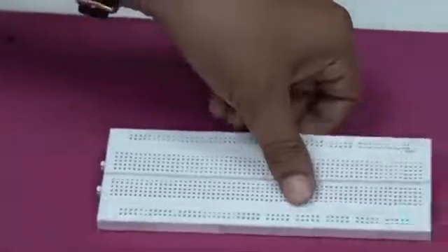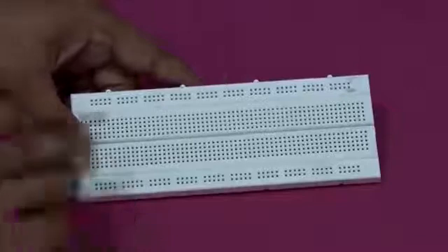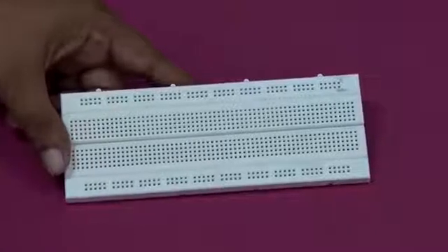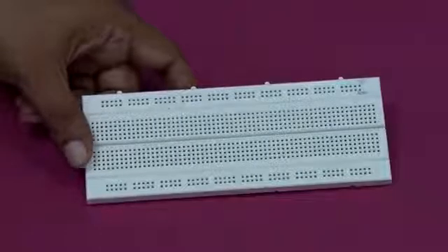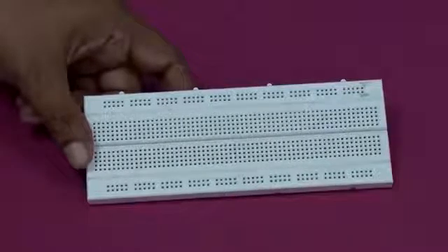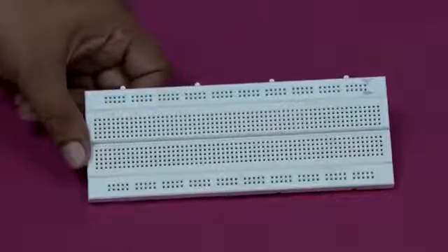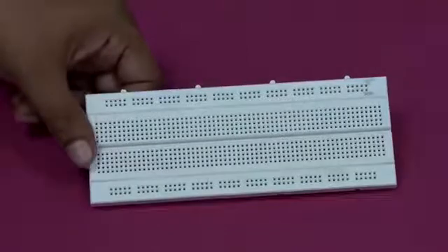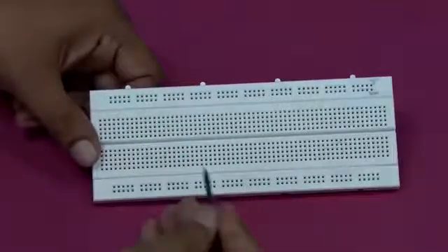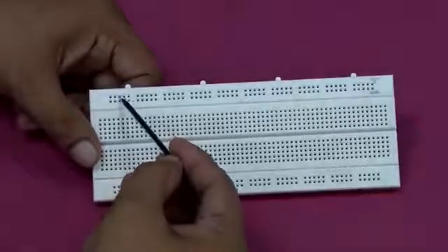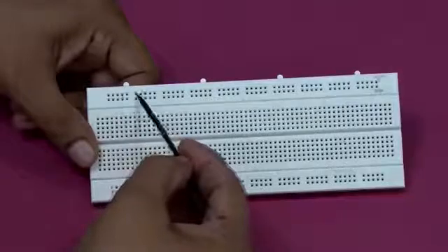So, now Ranjit has to help me. As I said, all the negatives of the battery, the black terminals of the multimeters, and the emitter are all connected to the zero potential line. They have to be connected to each other, which we will be calling zero potential. So, on this breadboard, I will be using this line here for that zero potential. They are all connected to each other.